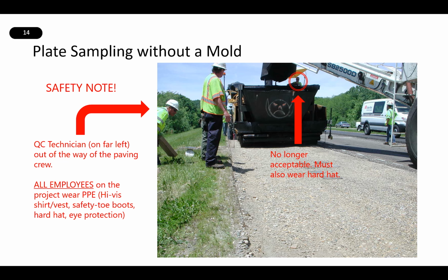This slide just serves as a reminder to always stay safe when out there taking samples. It's important to make good eye contact with the operator of the paver and the transfer machine before placing the plates down, and to try to minimize any walking in between these 2 pieces of equipment. Always wear your proper PPE. Hard hats and vests are required.